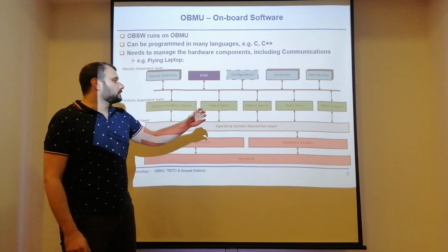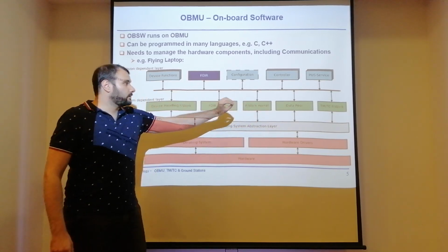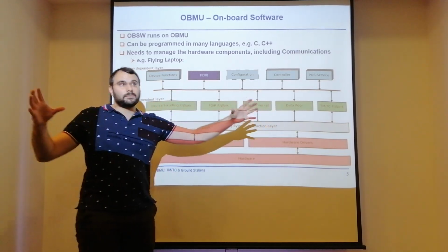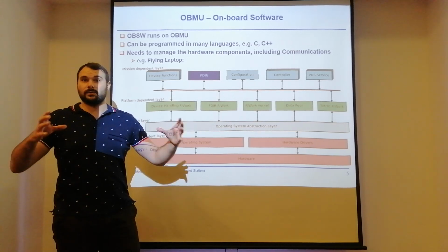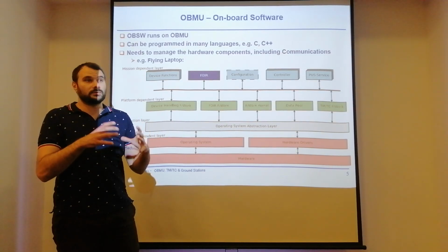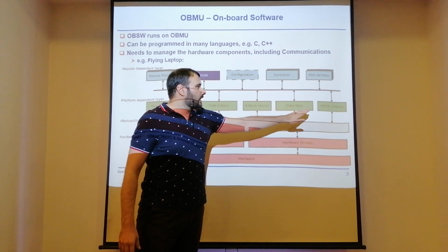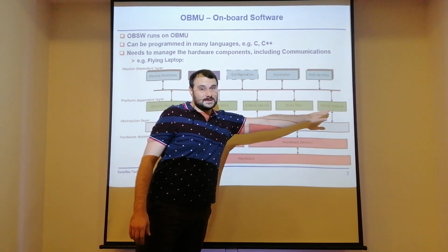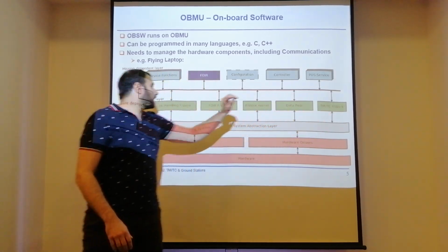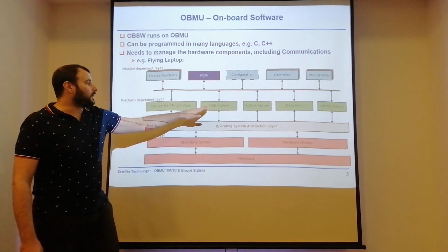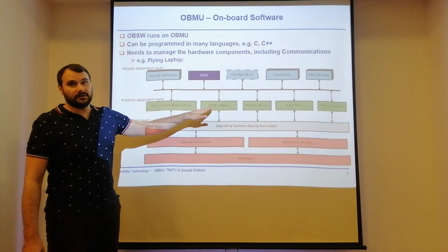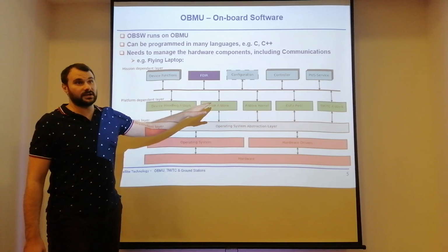We have our kernel framework, we have our data pool, where all the information from our sensors and our onboard telemetry we are recording come together. We have our communications TMTC framework. And of course, we have the framework for our FDIR, our failure detection and isolation and recovery system.